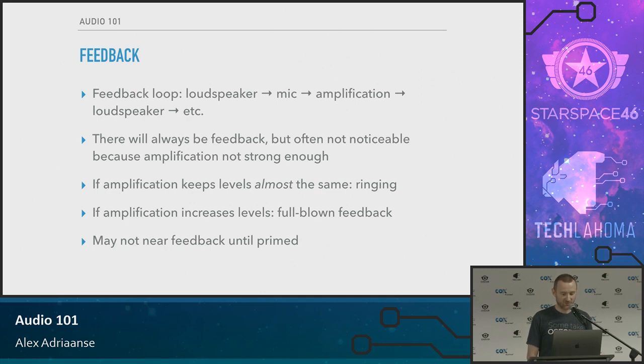But if the amplification levels get close to where the sound coming out of the speakers is, and then being picked up and making its round through the sound system, the second time it goes around, if it's almost at the same level as it was in the first round, then you'll start hearing ringing. It still dies away after a while, but it's kind of an obnoxious sound. And then if you increase amplification even more, where in the second round the audio levels are louder after having traveled through the sound system, then you'll have full-blown feedback.